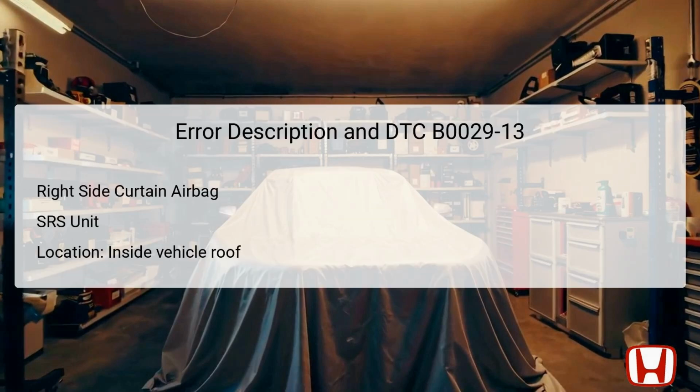The error DTC B0029-13 signals a fault relating to the right side curtain airbag's first inflator. The right side curtain airbag is designed to deploy in side impact collisions, protecting passengers from injury. It is typically located within the vehicle's roof lining above the side window areas. This airbag operates via an inflator that, when activated by the SRS unit, releases gas to inflate the airbag within